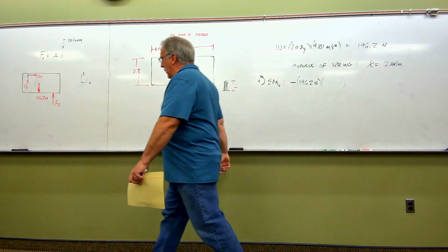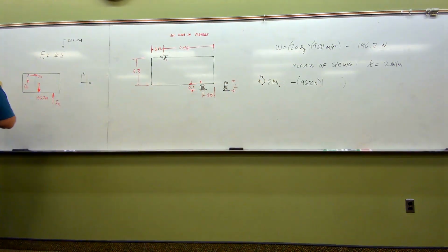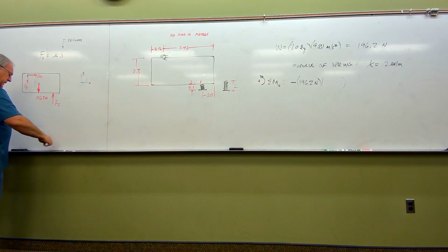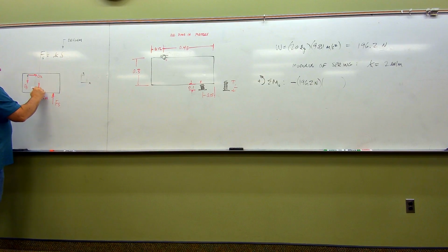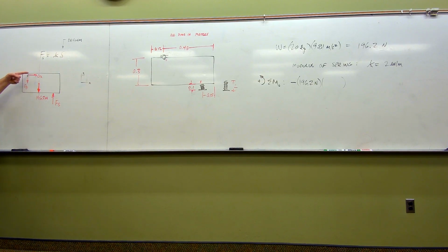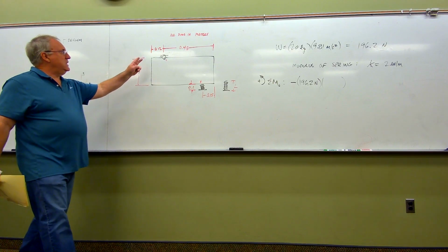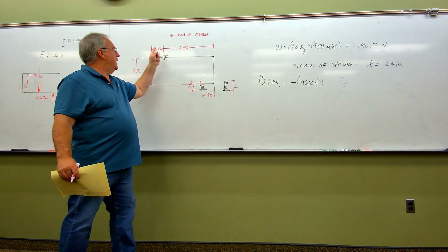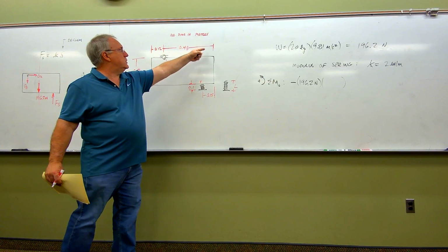So my moment arm, folks, we'll all remember, is simply the distance from my moment center to the line of action of the force, and the line of action goes forever, that distance making the 90-degree angle. So I need to know the distance from here over to here. If I go back to my original diagram, you've got to kind of synthesize this one a little bit. We see that the overall width of the plate here is 0.12 plus another 0.48.